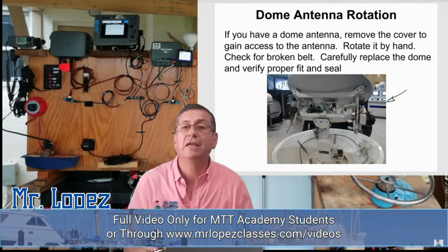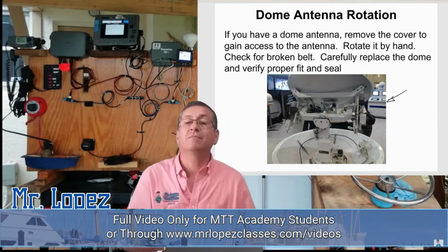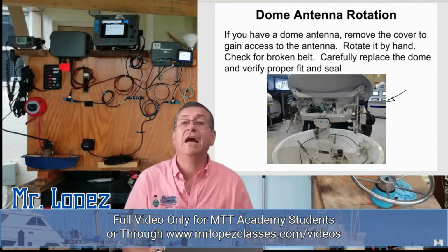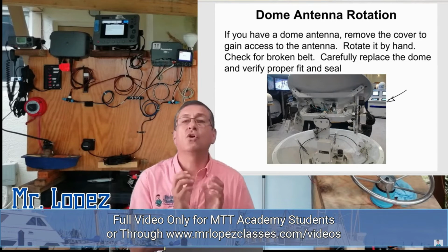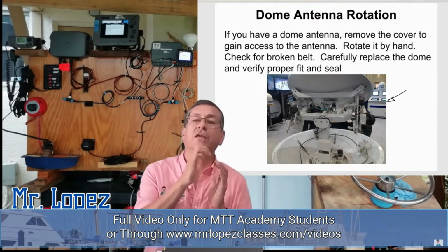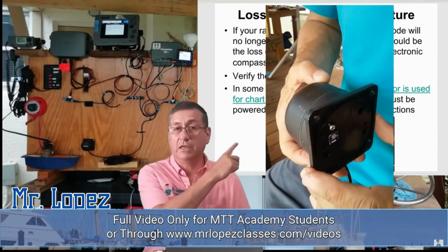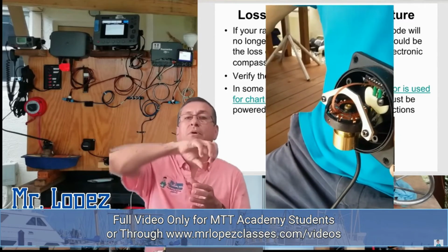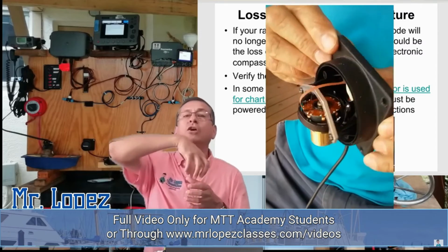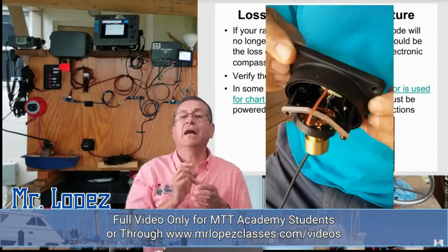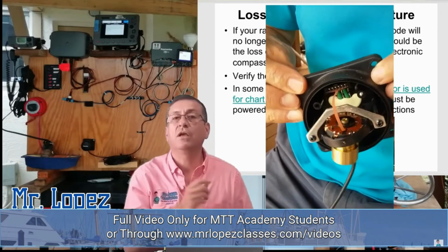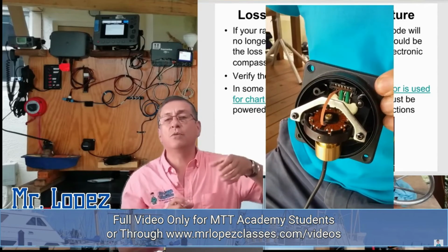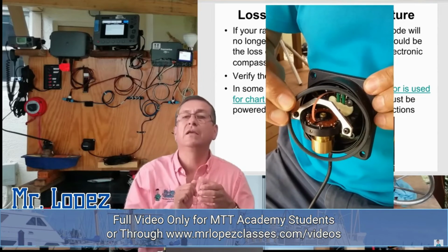If the O-ring is broken, humidity enters the system and produces erratic information and corrodes the computer, corrodes the feeding with the cables entering the computer. Be careful with that. Normally, if you open that sensor, that's the picture that you have on the screen right now, you have like a gyroscope. That gyroscope should be completely free. This is the gyroscope that you have on the screen right now. Verify, move the gyroscope with your hand and verify that it's free.